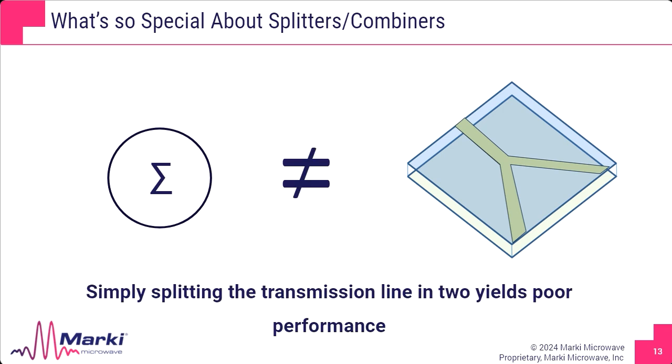First, you're going to run into reflections and impedance mismatches. While the voltage on each branch of this divider will remain equal, the current needs to split between the 2 of them, and this can't happen instantaneously for a wave. So no matter what in this design, you will get reflections. You can mitigate the reflections by making these output lines half as wide, but now we have a new issue, which is that these output lines have a different impedance than the input, again, disrupting signal integrity.